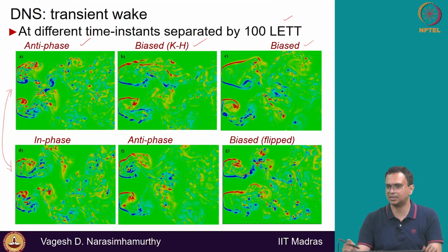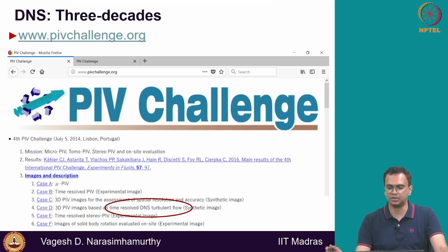So basically this is just an example, but you have to be careful that sometimes when you run longer, especially when you have instabilities in the flow, it can suddenly show you a new result, a new flow profile. You have to be careful when you perform statistics. If I am averaging now at 600 large eddy turnover times, I will get a view which is time averaged between all these 6 flow fields, which represents neither one nor any of these. It will show something else. You have to be aware of this.